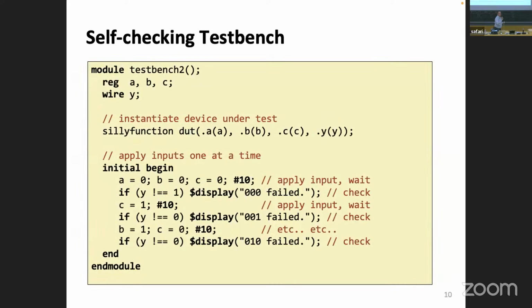This one. No, this is the one. This is the one, this is the new one. So now it's exactly the same, but now we are also adding the comparison in here. We are saying, hey, is y equal to 1? Then comes this funny thing, $display. Well, $display is an internal function of Verilog, and it does type out to the standard output, in this case, the console of the simulator, whatever message you have.